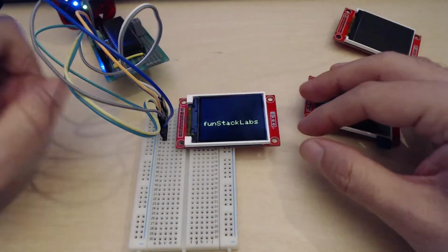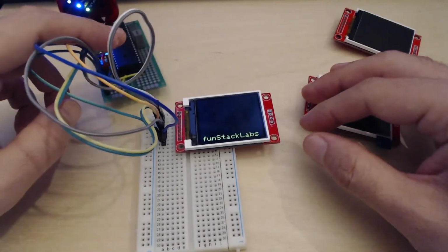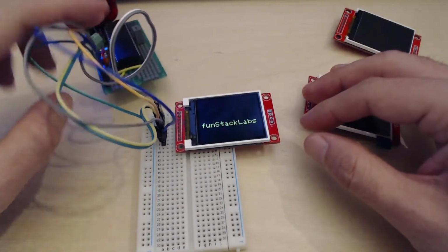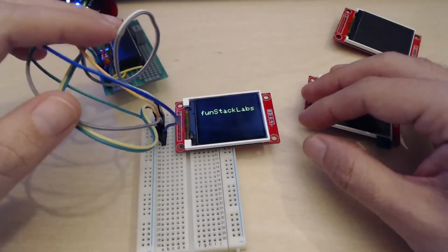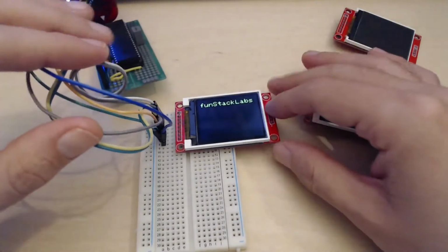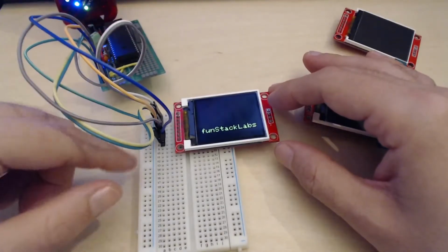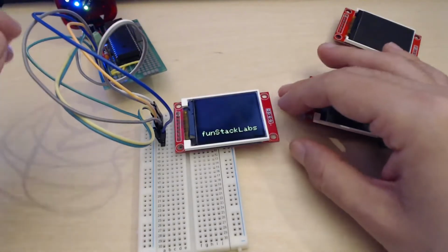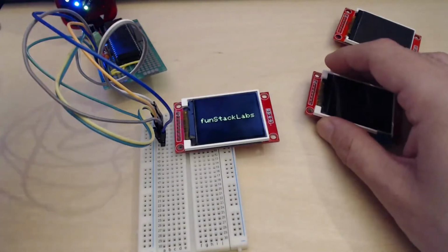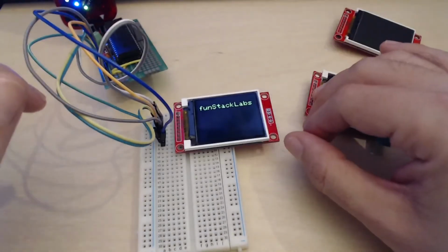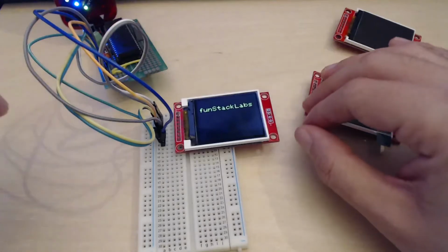It's also quite important that you have some kind of capable micro for it. Many micros out there can drive those displays, but you need some pins. In this case, it's a 4-wire SPI. You need 4 pins, but a little bit more than that if you want to drive the backlight intensity and all the other stuff.